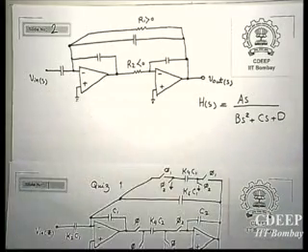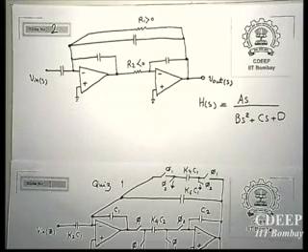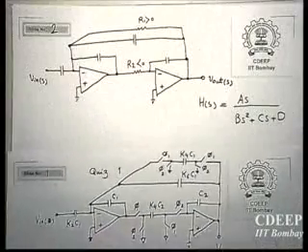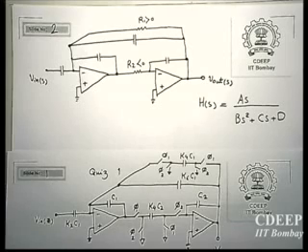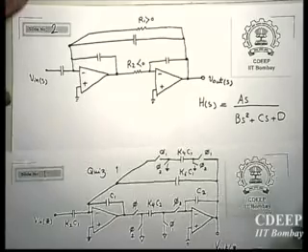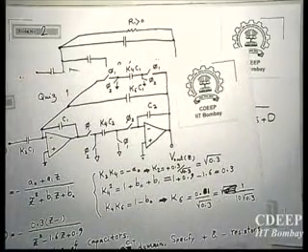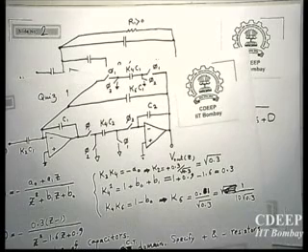And S equal to 0 means a 0 at S equal to 0, right? This will be translated to a 0 at Z equal to 1, which is a bandpass filter. So this is the simple biquad. Okay, I noticed many of you have derived it and also have done more, like for example, drawing the signal flow graph.